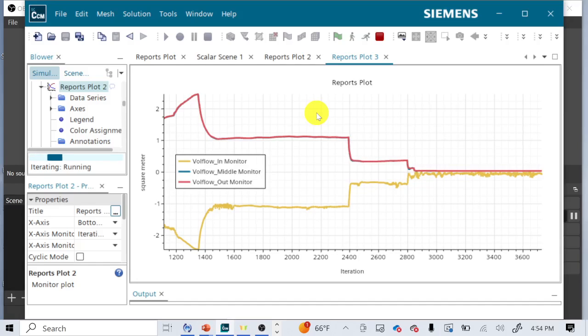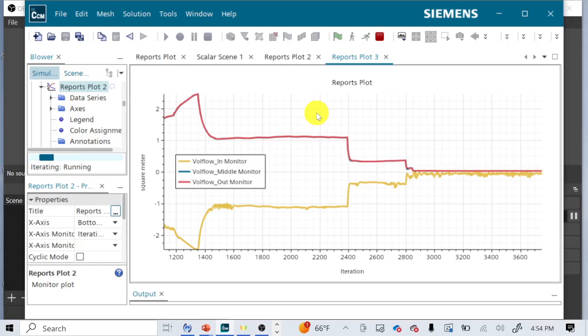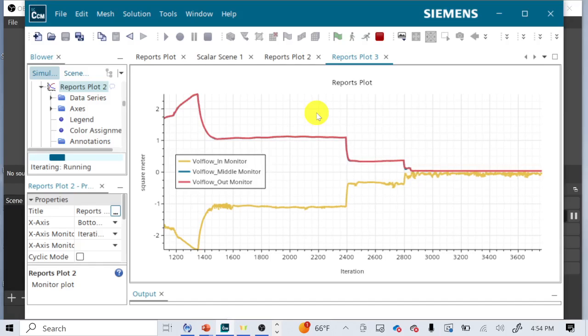But that said, I think if people would like help with the simulation, we can do that at this point. If not, then we can go ahead and wrap up for today. But again, do not forget that resistance section. That is what lets us actually figure out what this fan curve is. If you don't add that block on and are able to add resistance to this thing, you can only really get 1 data point, which is not enough.